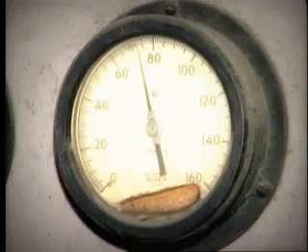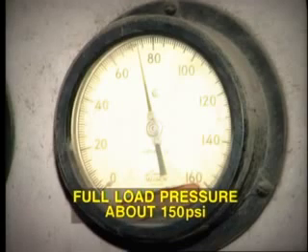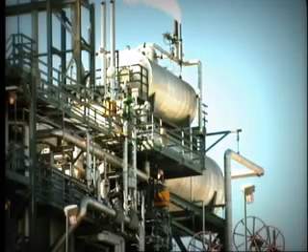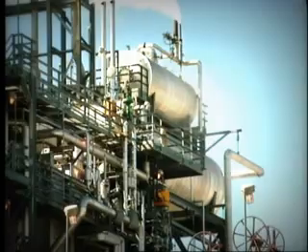The pressure inside the de-aerator varies with the extraction steam pressure. At full load, this is likely to be, say, 150 psi. However, at lower load, this pressure would be considerably lower. Often, the de-aerator is located at a high elevation in order to provide a positive pressure to the suction of the boiler feedwater pump.